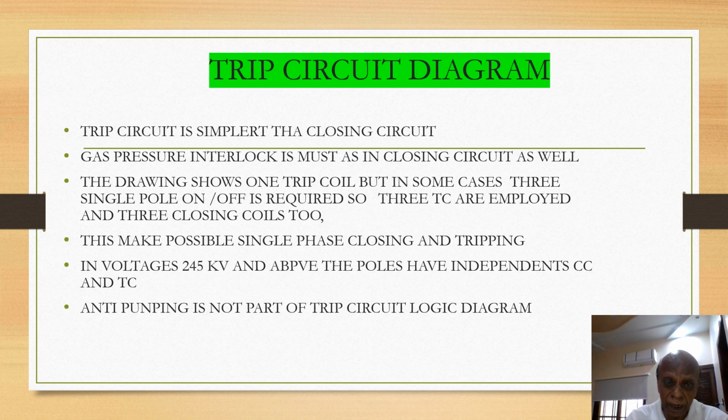That circuit diagram I will discuss separately. Here I am not mixing it up, but just explaining in case you come across a drawing where you have two sets of trip coils and two sets of batteries, and there is another third type of tripping. If both the batteries fail, then ultimately there is an arrangement with a charged capacitor, and the breaker is tripped by the use of the DC from the capacitor.